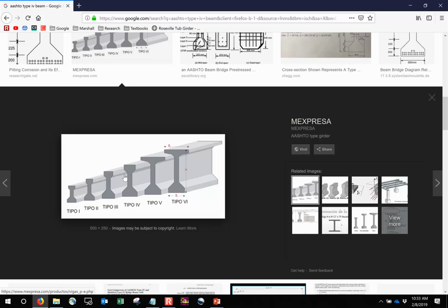Now, how do you determine the moment capacity? Well, let's assume for the sake of discussion that we don't have to consider pre-stressing. All it is, is determining where that depth is such that C equals T, and then finding a moment arm. Now, is your stress block a little more funky? Yeah, your stress block's a little more funky, but you all took statics for a reason, so that you could determine centroids and moment arms and things like that. So all you'd have to do is say, okay, here's the point where C equals T. Let's determine the centroid of this shape, determine that moment arm, and plug them in. So I don't want you to think it's impossible. I'm not going to make y'all do that in here, but I don't want you to think it's something that you can't handle, because you, of course, can.